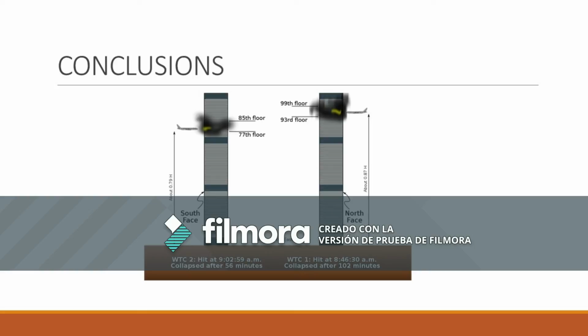After seeing all the calculations that we made for the project, we conclude that by itself the crash of the airplane didn't have a significant impact on the fall of the building. However, the fuel of the airplane was the main factor in the failure of the structural system. The structural steel melting and the speed at which it did were detrimental, so that the structure was losing all its lifting capacity, and finally a domino effect was created. In the end, the whole building collapsed. Our numbers show that the load of the floor was overcome, and that creates the failure of the structural systems.